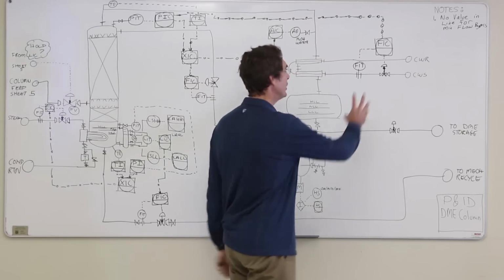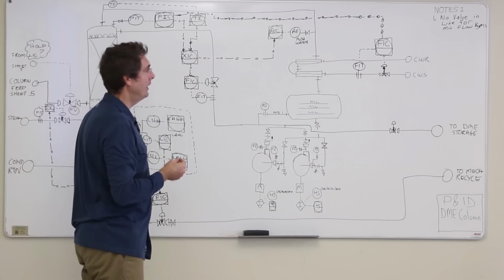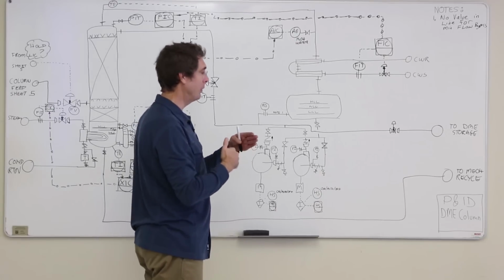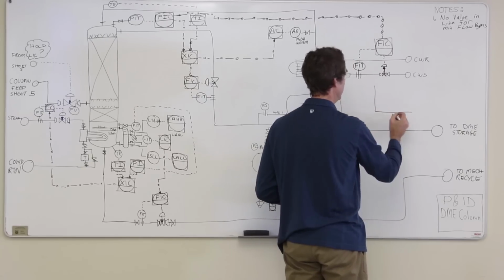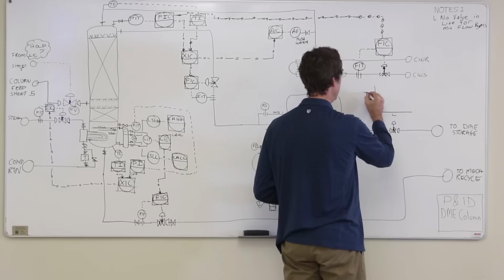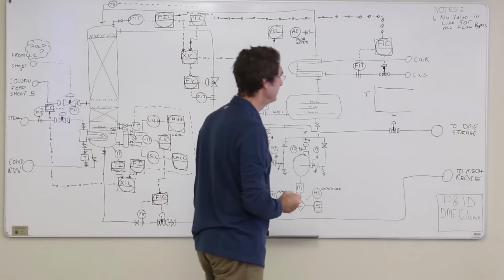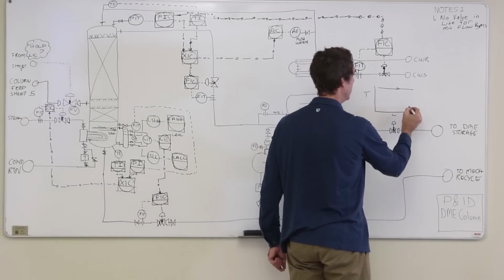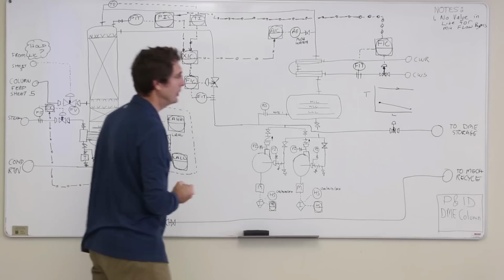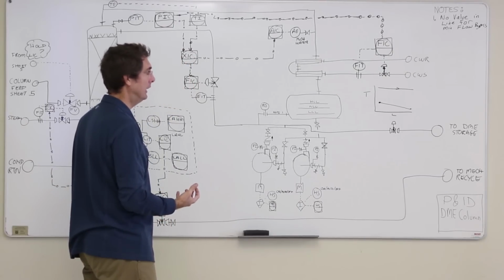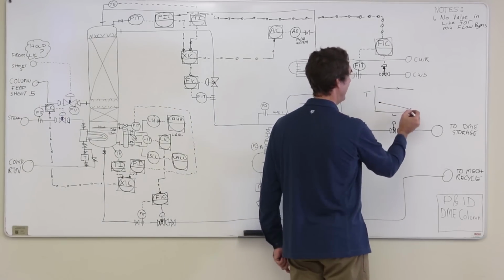But essentially what happens, if you start to throttle this control valve, then the result is heat exchangers all work with LMTDs. So here's the length of the heat exchanger, or the Q value, the heat flow across the heat exchanger. Here's the temperature here. Here's our hot stream, like that, and our cold stream comes in at some low temperature here, and we probably have a design kind of like that. If we start to reduce the duty on the heat exchanger and start restricting the flow rate in order to reduce the duty, that temperature is fairly fixed.